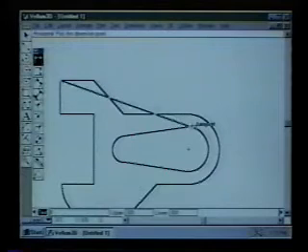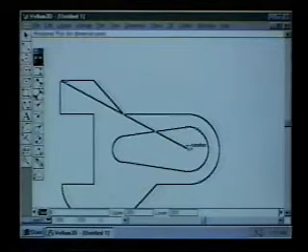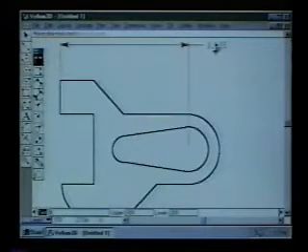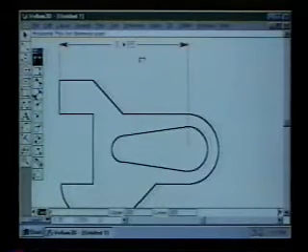And then the drafting assistant will snap right to this endpoint. Then I can come over here and wake up these arcs and go to that center and snap right to that center. And then it puts a dimension right on there for me. I can take this up and slide it clear outside if I wanted to. What I'm actually going to do, though, is specify a value for this, and I can even go beyond that and assign it at the bottom of the screen.